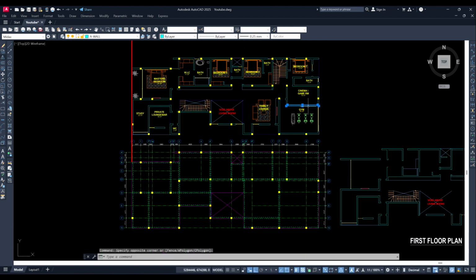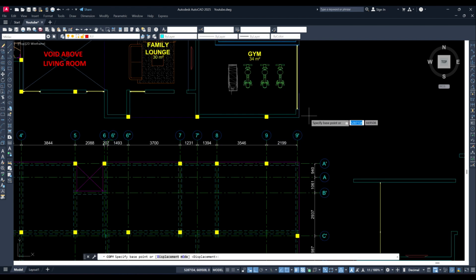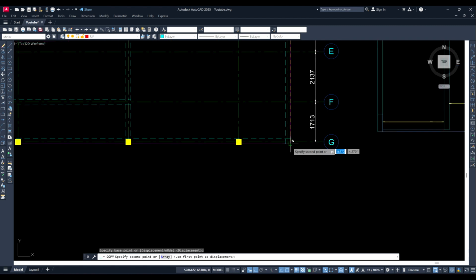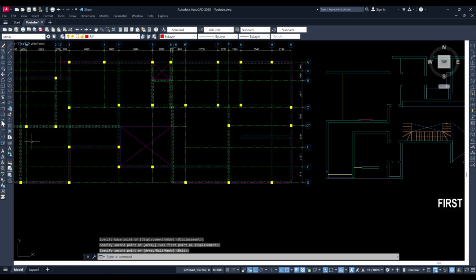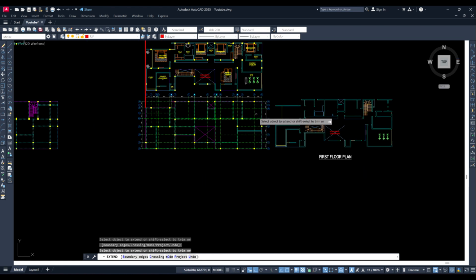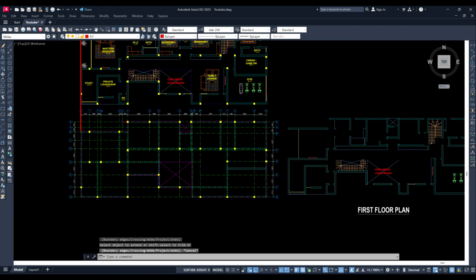Now I've introduced this beam. Just copy this, and that's a good point to pick. Then put it there. I'm choosing this beam here because I noticed that area, that span, is looking too big, just to reduce the load there and